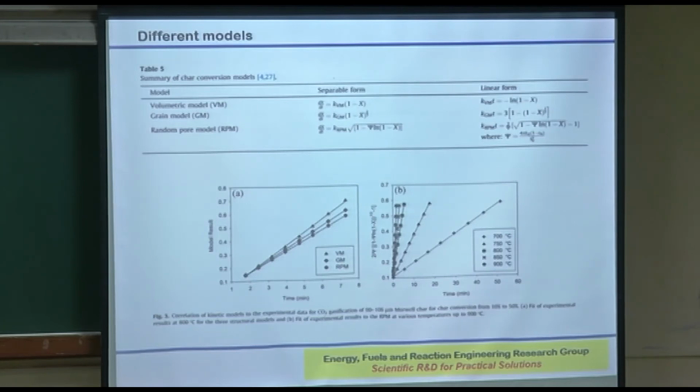So to you it is clear. For the benefit of everyone else, let me tell you, if the temperature is very high, who cares what the structural parameter is, because I will be able to convert the carbon with the help of the high amount of energy supplied at the high temperature.